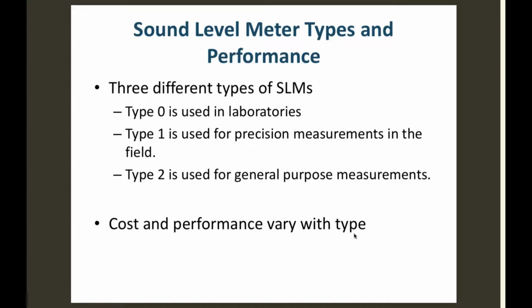108? Yeah, why is it not 114? Because it's not enclosed. In other words, it would normally be completely enclosed. It would just barely slide in here, and it would actually read 114. This instrument I know is calibrated, right? So if I had the right sleeve for it, it would read 114. So now I know that this thing, at 1,000 hertz, is reading properly.